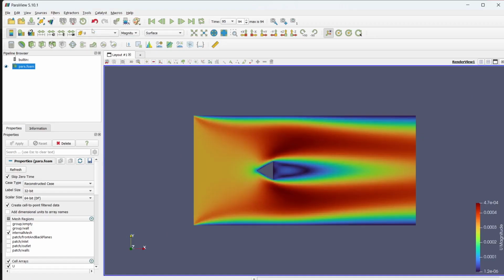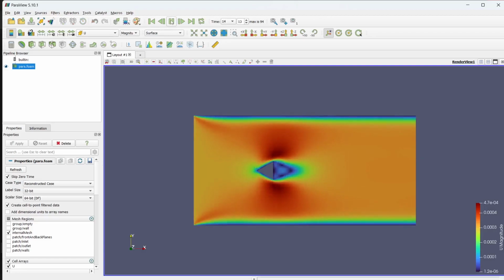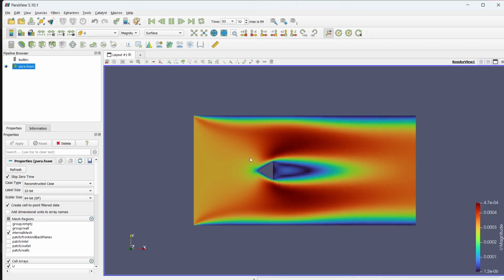And if I go to velocity, we can see that the solution is converged. After this, it is very steady state, the flow is not changing. But if you want to visualize it, you can press on this button, so we can see how the simulation propagated to reach the steady state. So this is the last time step over which the simulation will be totally steady state.